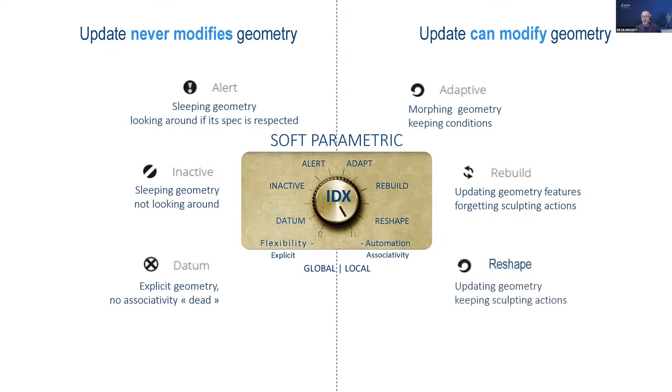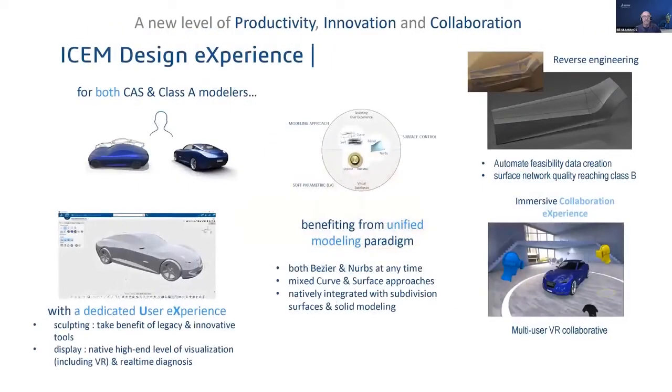Reshape mode is when you build a feature like a blend surface created by 2 curves, but still have the option to manipulate the internal blend surface control points. This is all while keeping the connection with the elements that constructed the blend originally. Last, revert. If you're not satisfied with the sculpting changes made on the surface, you can return to the original condition during construction.